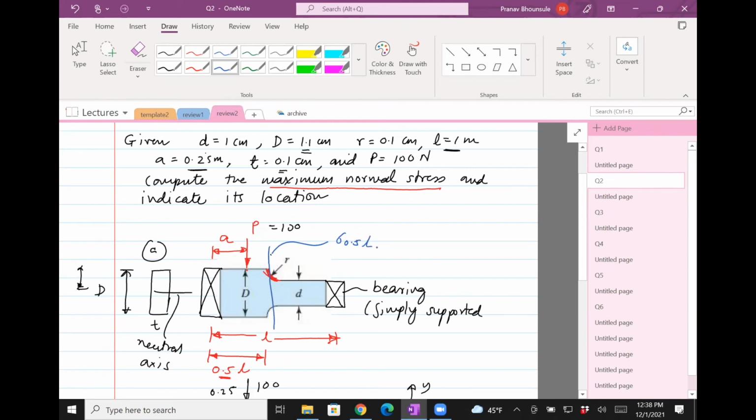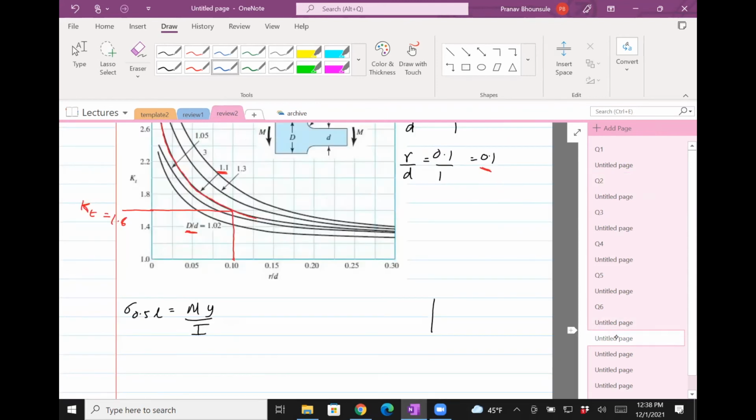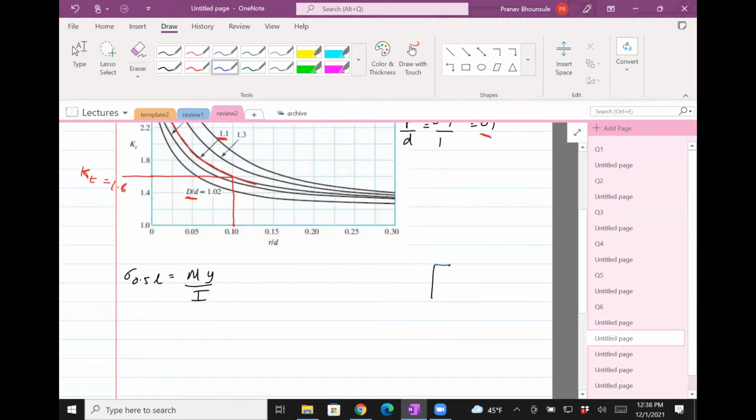So we're looking at not the larger diameter, but the shorter diameter, because that's where the stress is higher. The smaller the diameter, the higher the stress, because they're inversely proportional. So let's go and draw that first. That's small d, and that's the thickness.